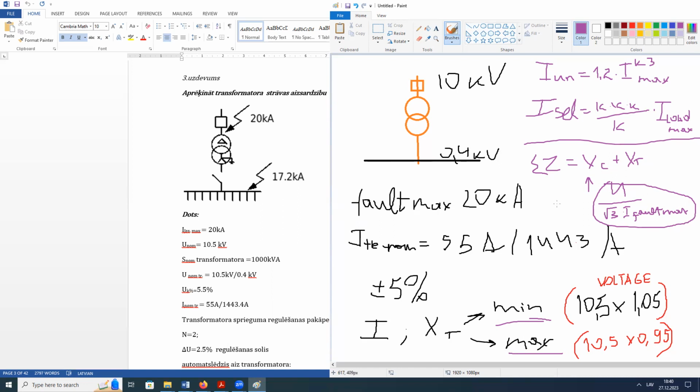Every time you calculate the fault current value using Ohm's law, you should calculate the resistance and choose which transformer resistance you will use, the minimum or the maximum, based on whether you are calculating the minimum fault value or the maximum fault value. Is it clear? Yes, professor.